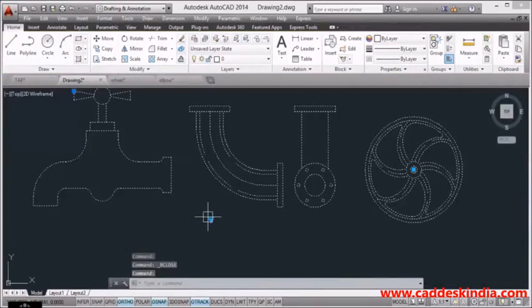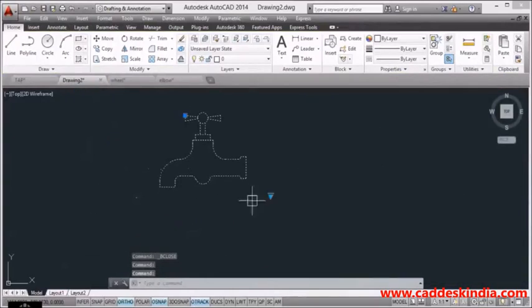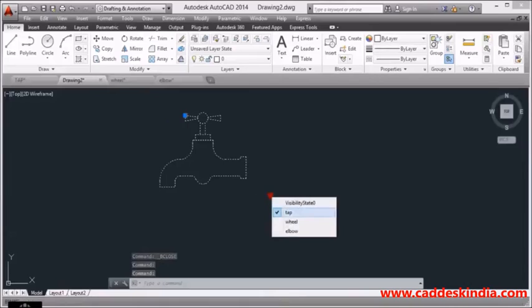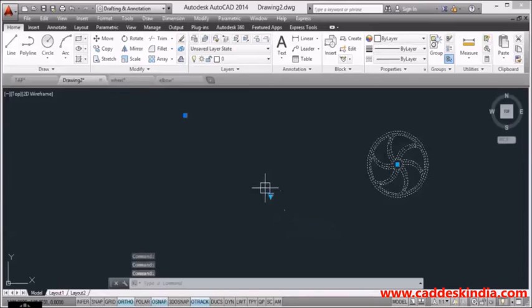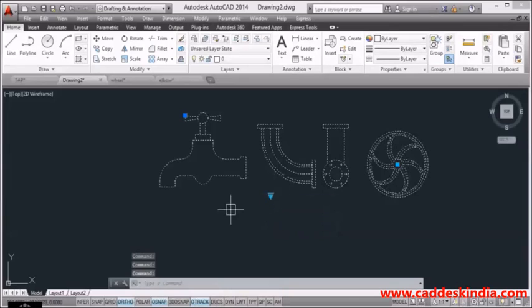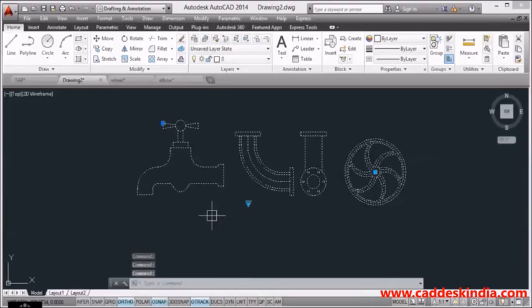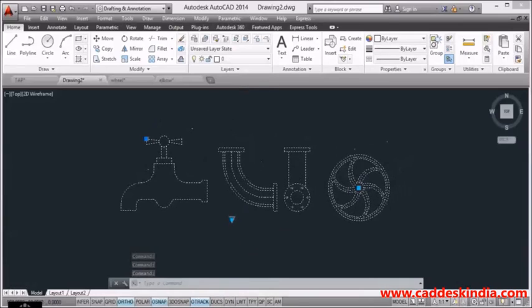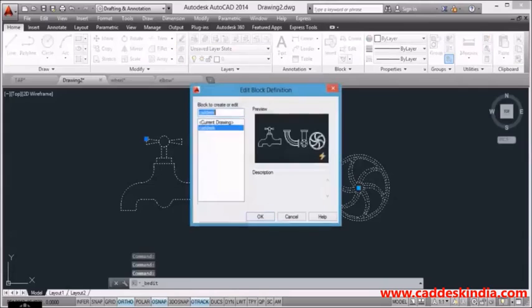Now you can see my parameters are here, and the view you select from this arrow is the only one visible in my viewport, and the others will disappear, as I described in the block editor definition.